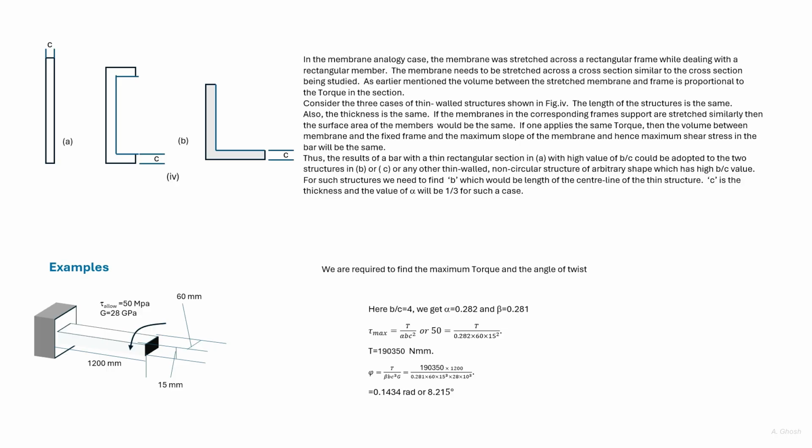In general, any cross-section can be taken. A frame has to be the same as the cross-section. A membrane has to be stretched over this frame and subjected to pressure. Then, as previously, we can find out the magnitude and the direction of shear stresses using the bloated membrane.